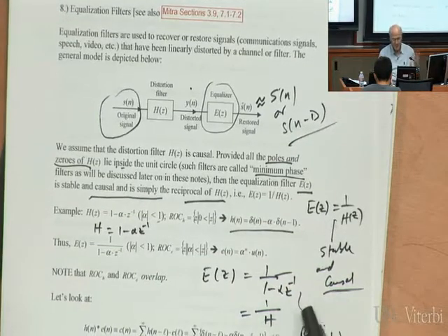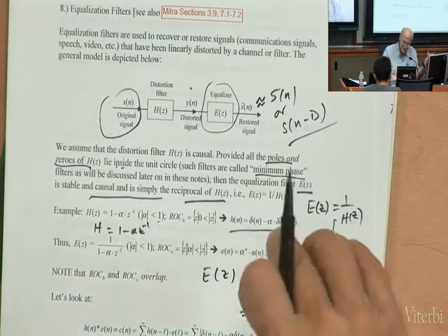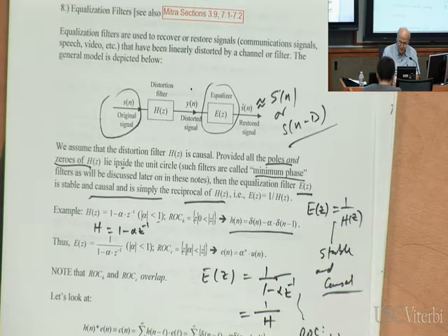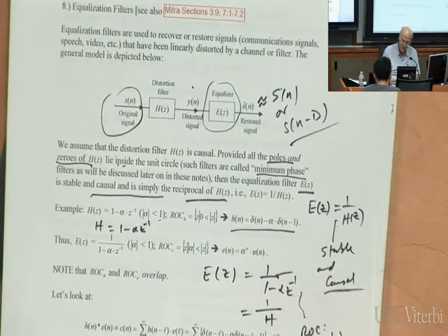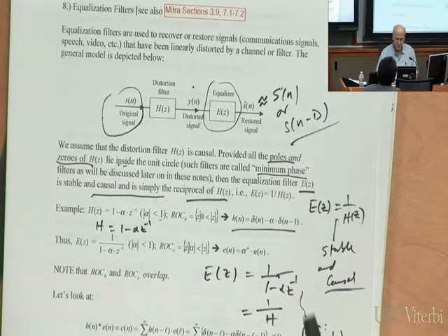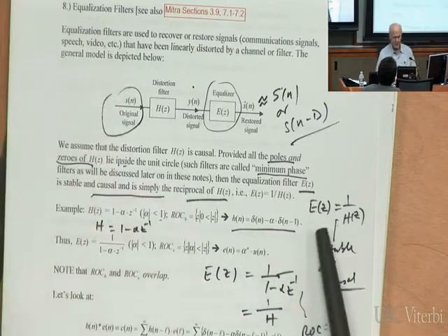So, is the filter stable? Is the unit circle in the region of convergence? Well, remember, we just said that the magnitude of alpha is less than 1. And it is external to that circle, so that implies, yes, sir, it is stable and causal. Wow, not bad. So that's pretty simple. So there's your distortion filter, done.